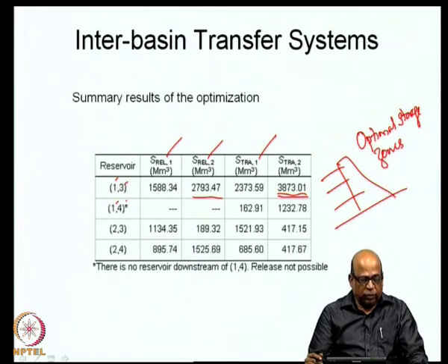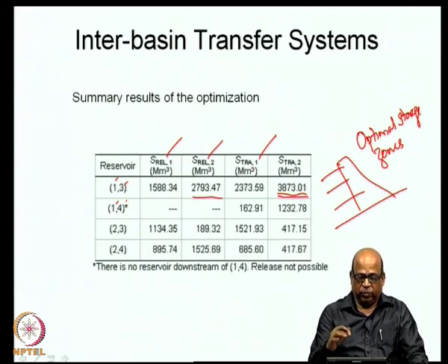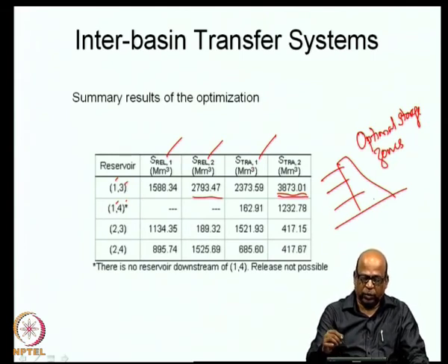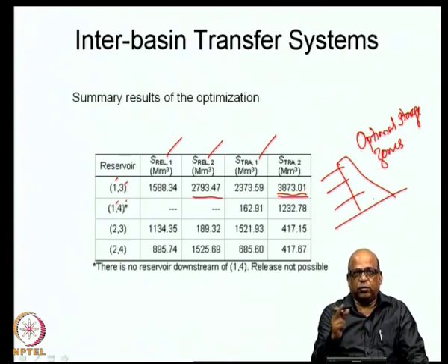Now, to answer that, we evolve several performance criteria. First level question is that at each of the reservoir, has it been able to meet the demands? We do all of these optimal storage zones and then operate according to the policy, the release policy, transfer policy, the diversion policy, etc. We do that at each of the reservoirs in such a complex system.